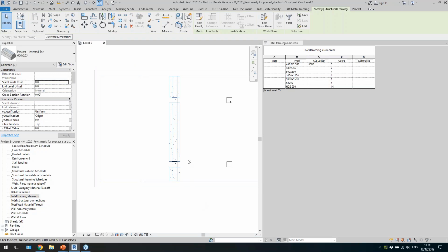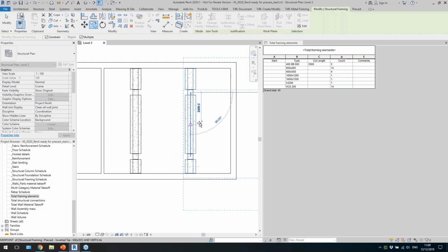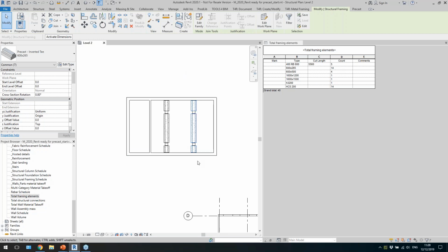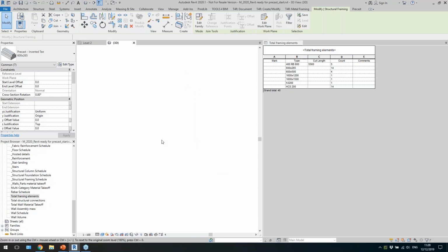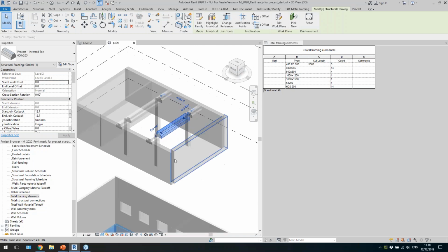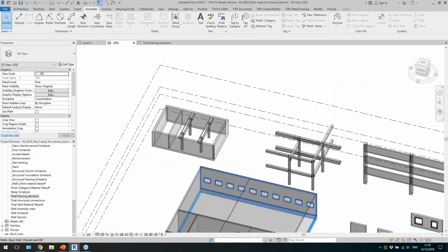But what I want to show is that in Revit, as I said, you create not only an element, but also different kinds of information. So when I have these beams, you see this is the type of 600 by 265. So the name is here. I have 7 of them in this model, but then I just copy them, right? So it's really obvious that it's now changed, it updates the number of these elements. So I selected more of them in here. So it's all live and it gives you all types of different value when you use BIM software.